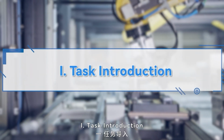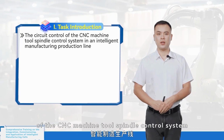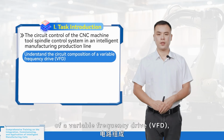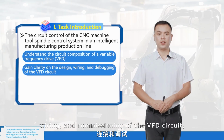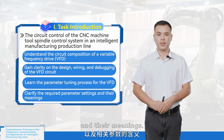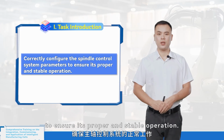1. Task Introduction. This task involves studying the circuit control of the CNC machine tool spindle control system in an intelligent manufacturing production line. Learners will understand the circuit composition of a variable frequency drive, VFD, gain clarity on the design, wiring, and commissioning of the VFD circuit, and learn the parameter tuning process for the VFD, including the required parameter settings and their meanings.